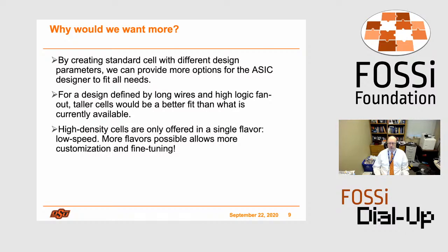And we also wanted to do a design that was not defined by long wires and high logic fan out. So we wanted to use taller cells that would be a better fit than the current SkyWater standard cells. We have high density cells that are only offered in really one single flavor, but we're always looking to tune this out, and I'll talk about some of the other flavors that we're currently working on, as well as the customizations.